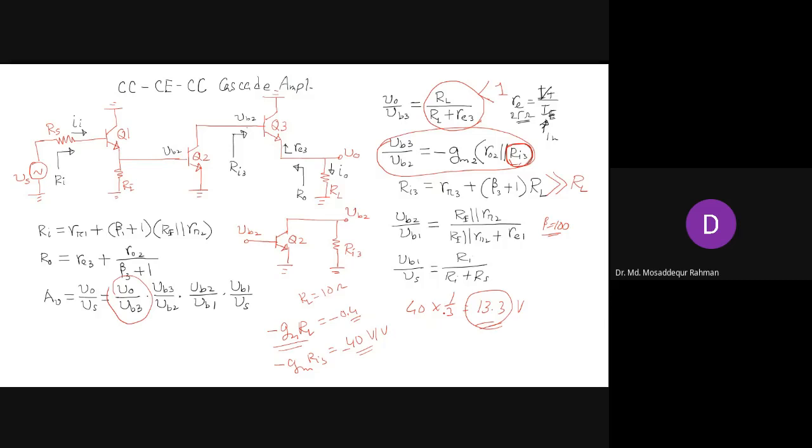At the output side, if your load resistance is low, that affects the overall gain, and you can overcome that by adding another common collector at the output side, which restores part of the gain. Now, maybe this is not good enough. Still 10, 20 may not be good enough for overall gain. So if you want to improve the gain further, what can you do?